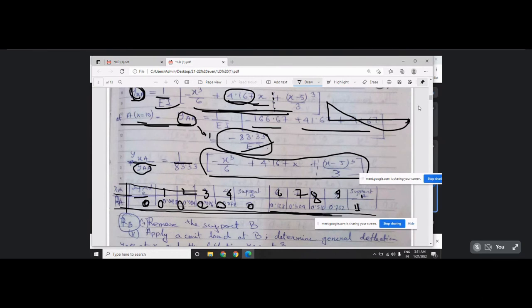So what we are doing, it can be done in many other methods, but this was the simplest and easiest for me. Just give a unit force here and measure the deflection at each point, and measure the deflection at this point where unit force is applied. Divide this force to all the ordinates. Okay, you can get the influence line diagram of RA here.